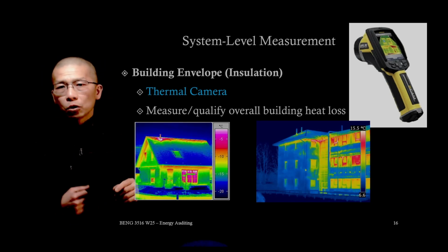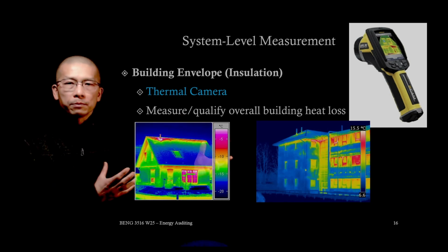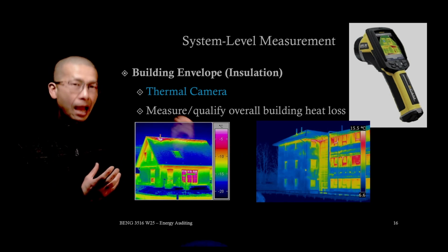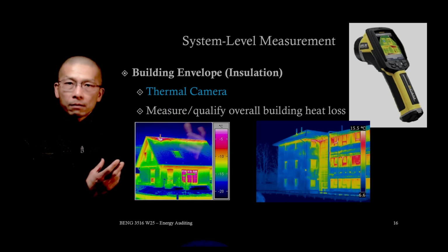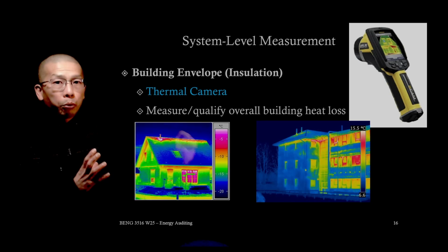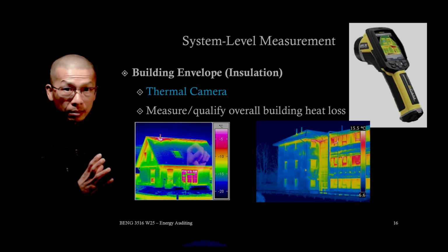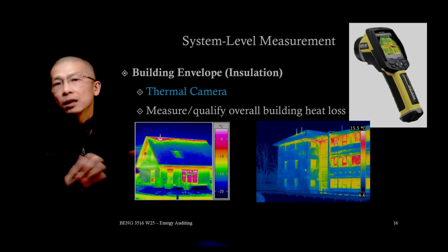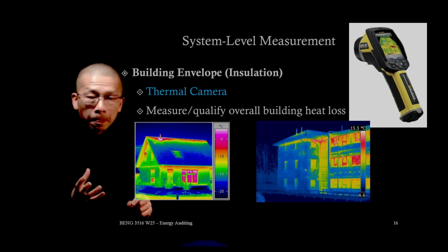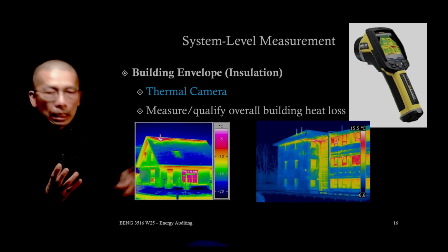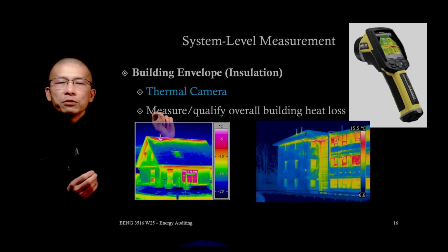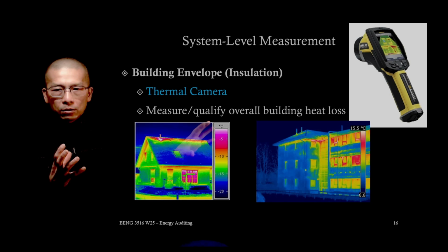And so thermograms are qualitative, not precise R value measurements. They are used to identify problem locations and areas, not to calculate heat loss directly. Okay, not directly. Be careful when using this kind of tool.